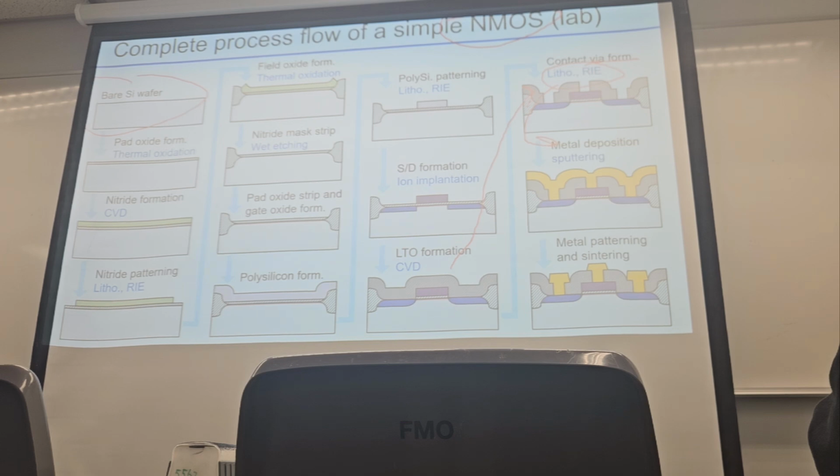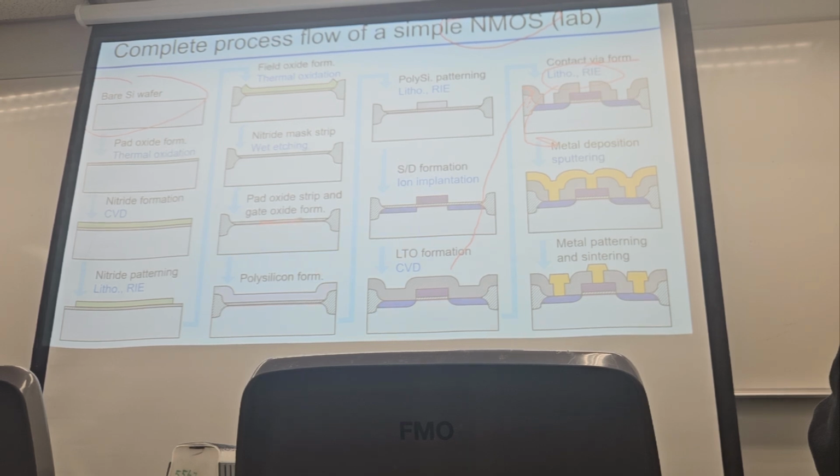Add an extra step to remove the silicon dioxide in a certain region to open the area for the Schottky diode. If we do not open it, then that region will go to the following step for the NMOS and the CMOS. Right? We remove the silicon dioxide, and then we can use the